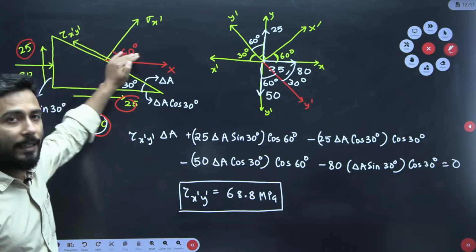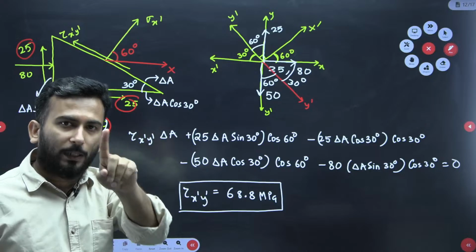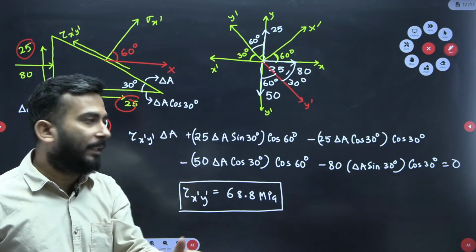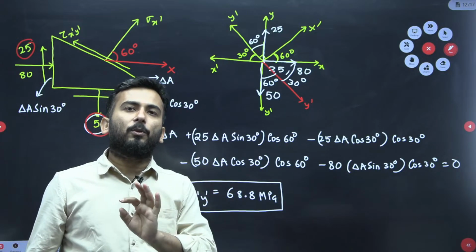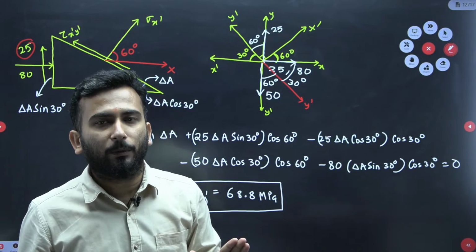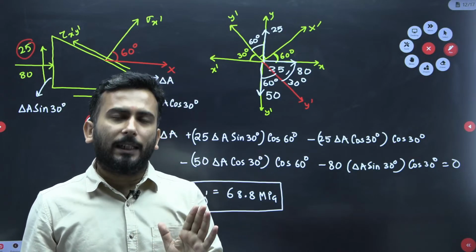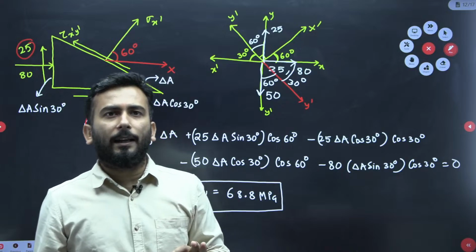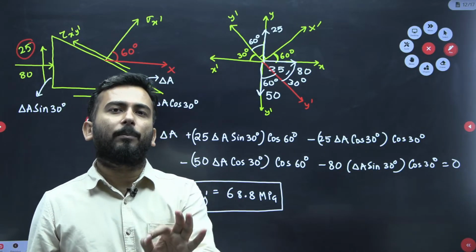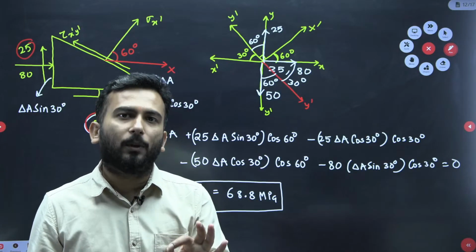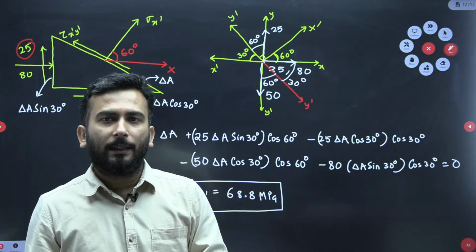So on this phase, I told you on a particular phase, one normal and one shear will be there, and this value I have found out. Mind it, I have not used a single stress transformation equation. I have not used anything. I have only applied force equilibrium. That means one thing you people are able to understand, that the basis or the origin of developing the stress transformation equations is force equilibrium only.